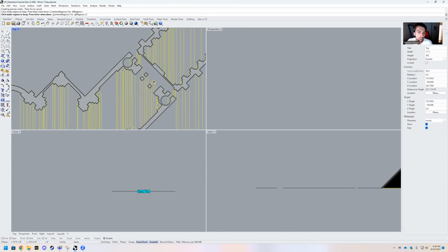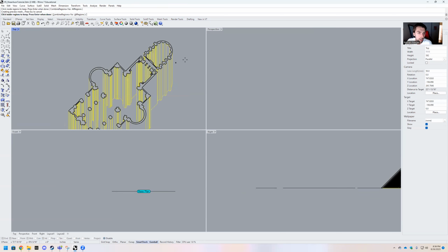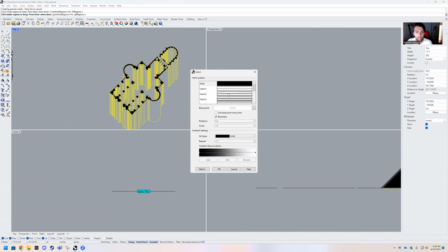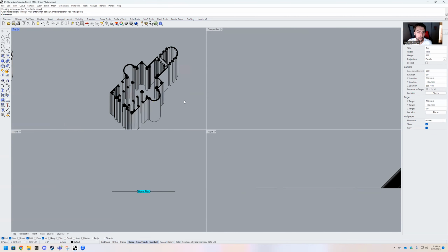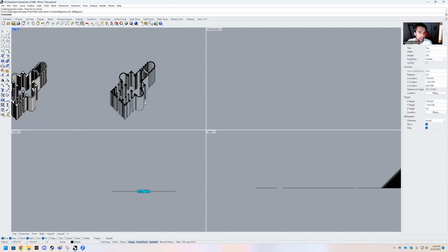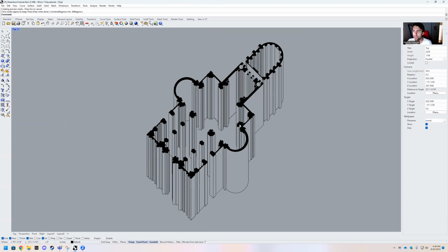So you can just click everything that's being cut through, right? Just like that. And when you hit enter, it generates a hatch, and you can make this solid, you can make this patterns or line work. I'm just going to keep it solid for now, for example. And just like that, you have a plan oblique drawing that you've quickly generated simply from a floor plan.